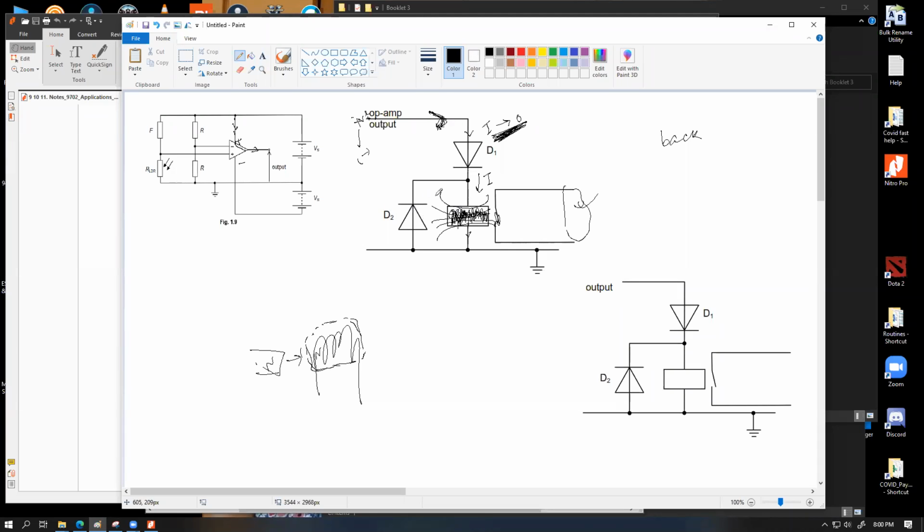So we do not want this high current to flow through the op-amp circuit. To avoid this flow through the op-amp circuit, we are introducing this pathway of wire over here. The purpose of this wire is that whenever this coil tries to pull a huge amount of current, it now essentially has a large high voltage over here. A very large current will flow from high voltage to low voltage, in this manner.